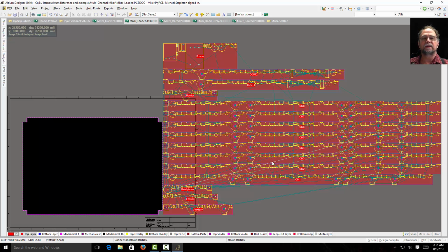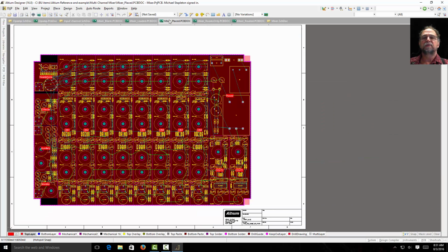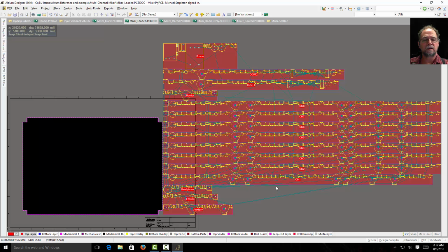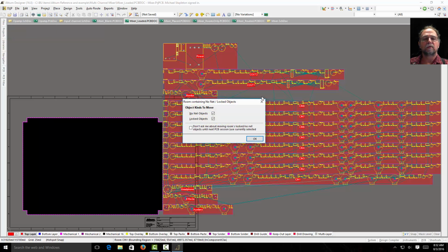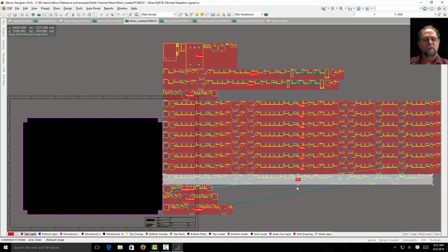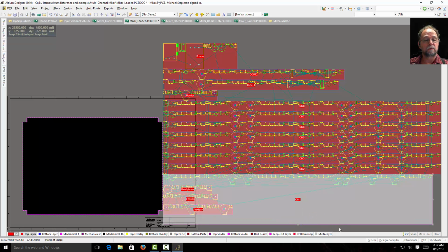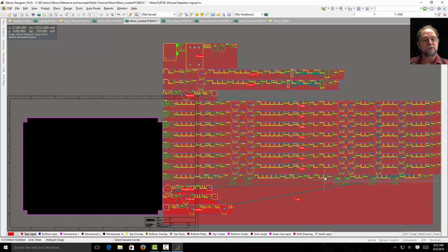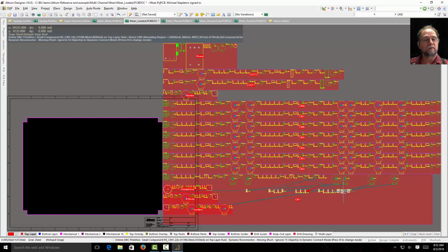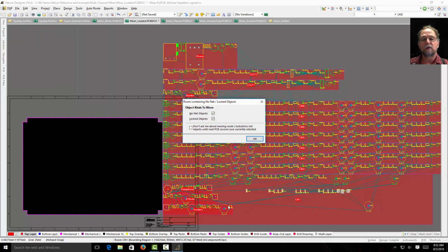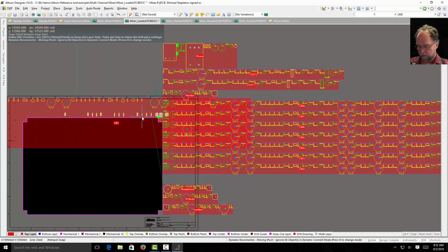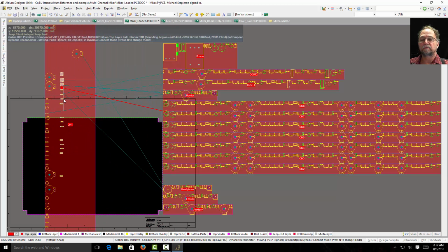And what's nice about that is with Altium, I can take one channel. You'll see them placed here. I can take one channel and say, let me take channel 1 here. And I'm going to change the size of the room. I'm going to make the room this big. And maybe I want to move these parts over here. And this thing down here. And I'll move the whole room. And rotate it and stick it here.